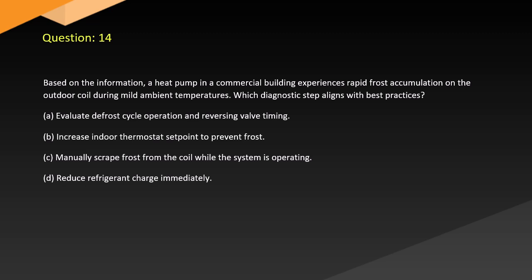Question 14. Based on the information, a heat pump in a commercial building experiences rapid frost accumulation on the outdoor coil during mild ambient temperatures. Which diagnostic step aligns with best practices? A. Evaluate defrost cycle operation and reversing valve timing. B. Increase indoor thermostat set point to prevent frost. C. Manually scrape frost from the coil while the system is operating. D. Reduce refrigerant charge immediately.